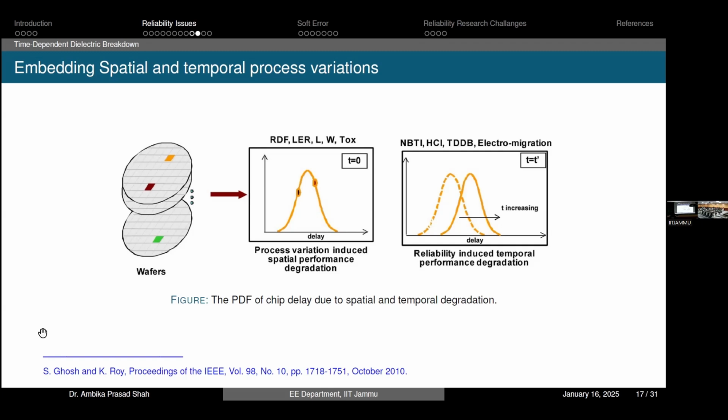You know that, let us assume this is the minimum delay that I can accept, and this is the maximum delay which I can accept. Beyond that, some of the samples may fail. If delay is in between these two, it means that your circuit is working properly. So if my distribution is something like this, there could be one more possibility.